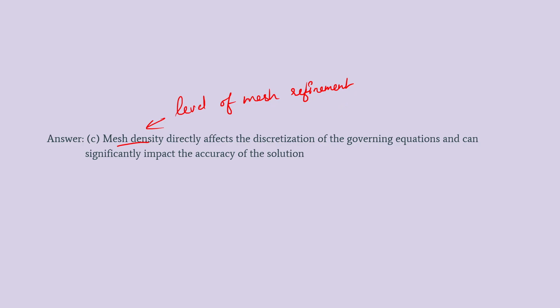So the mesh should be sufficiently refined, that is the geometric proportions of the cells should be small enough to capture the flow changes, the parameter changes for the CFD problem which we are analyzing. We aimed at finding some of the flow properties. Then the mesh should be reasonably fine enough.